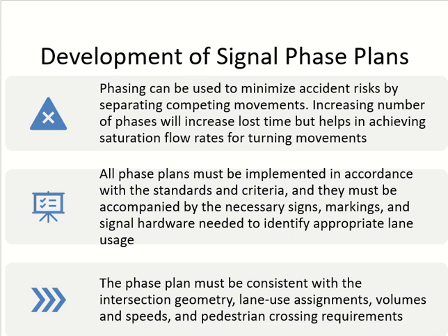Separate traffic signal, both directions. So you will have two poles with two different signals, one for left turning, one for straight. That's how the driver would know that I have a different signal which I have to follow. And sometimes you will see a traffic island between the two lanes as well. So all these things are done because of what? Because of the phasing plan. So once you decide the phasing plan, you have to also design the control devices at the intersection accordingly. Clear?